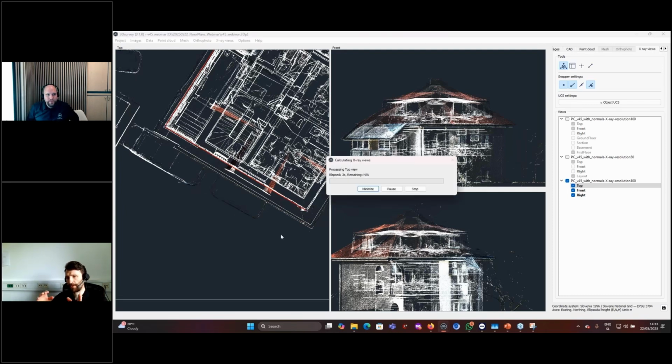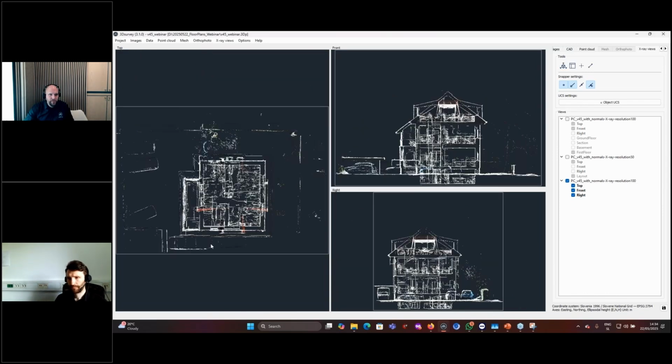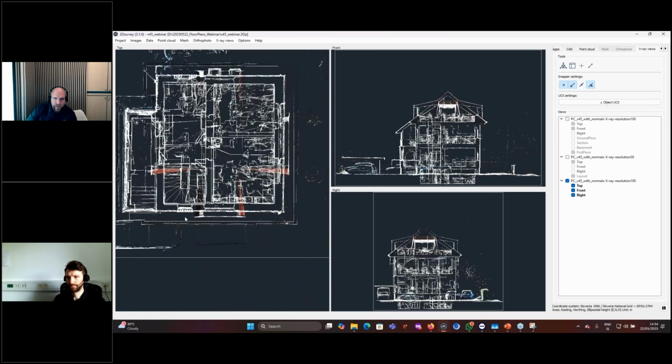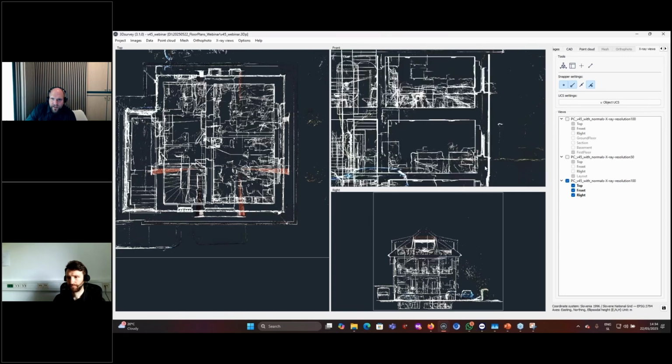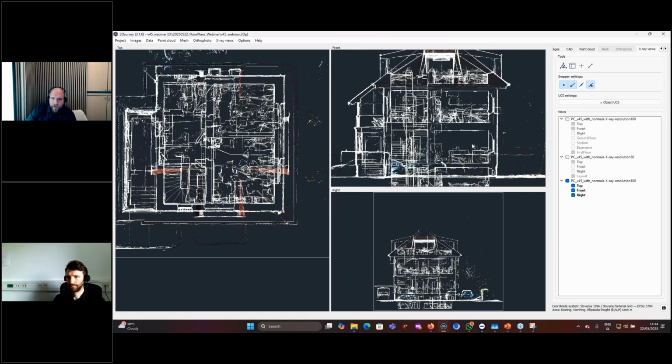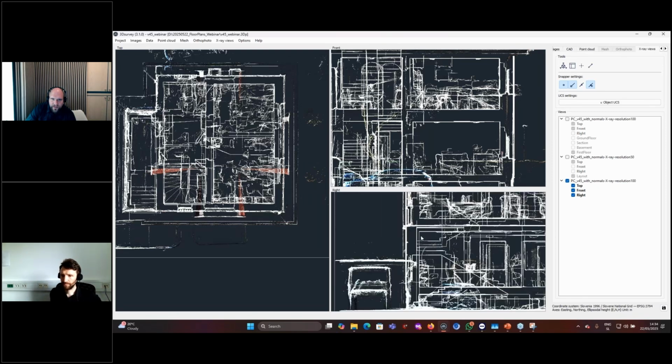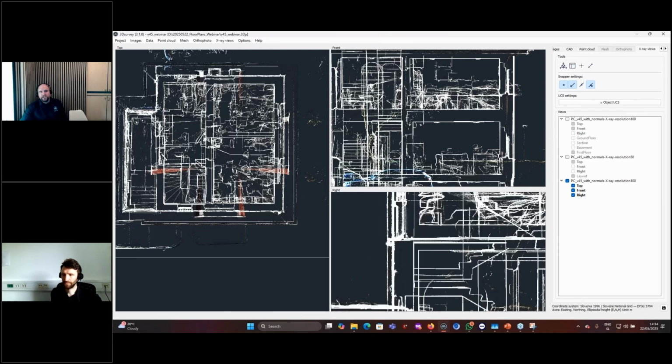So you started in a corner and you aligned it with the walls? Yeah, you try to find a well-defined wall and you just draw the line along it. It will also draw a perpendicular line. You want the entire model to align nicely with those two perpendicular walls. After we do that, here in our side views, we now also see through the side wall of the building. So this is the view through the front wall, and here we have the view through the right wall.